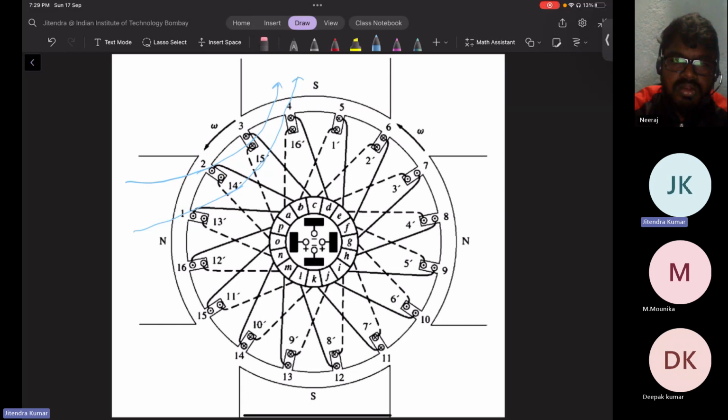Generally, the design objective is that all conductors should get linked. The worst case is when any conductors or any armature poles are left out of being linked by the magnetic fields generated by your stator magnetic field. So we design keeping in mind that all conductors should get linked. Otherwise, you are underutilizing your armature. Your armature will be underutilized with bad design.